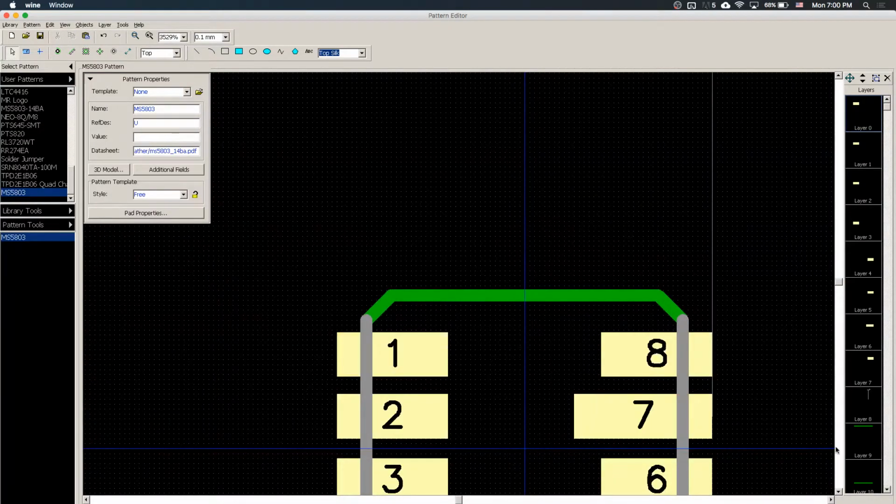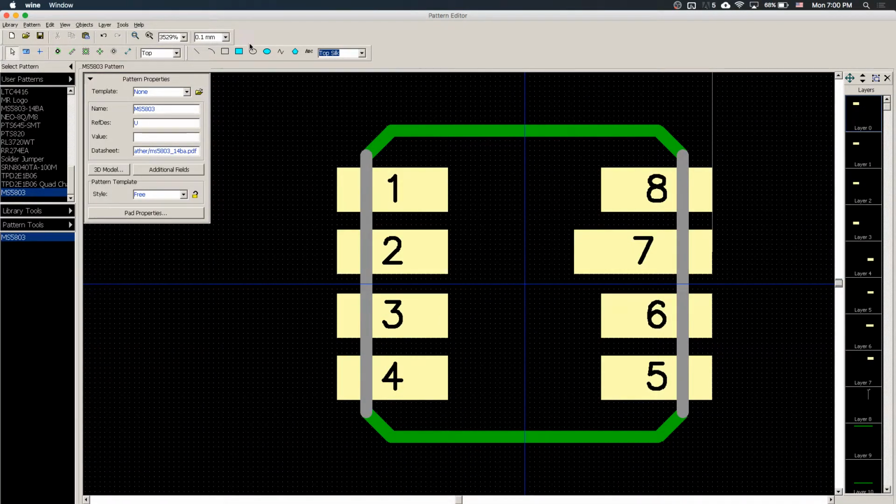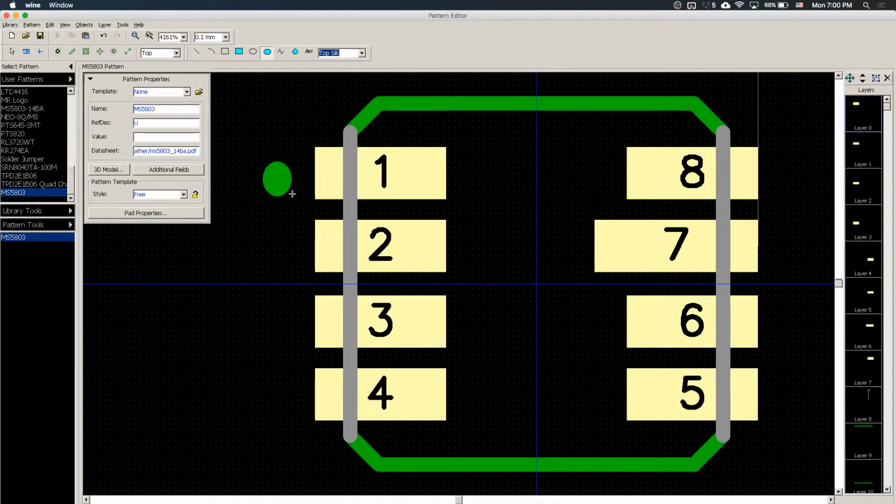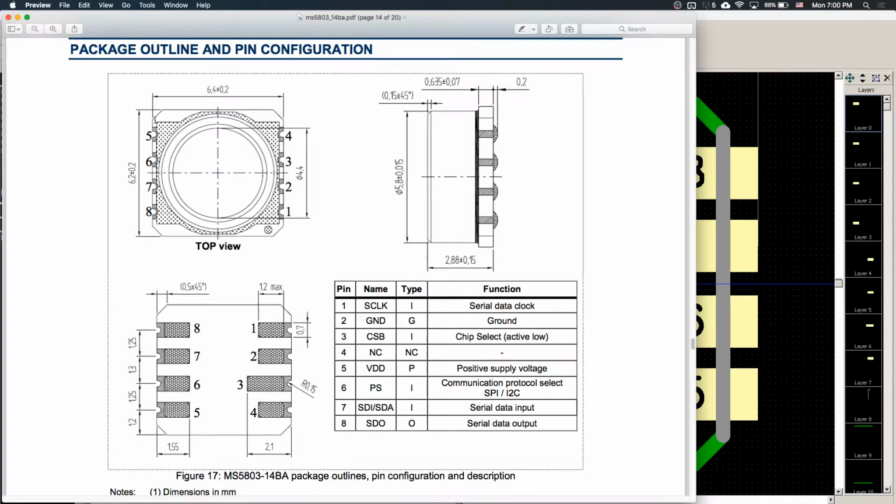The last one is a dot on pin 1, so just use the rectangular tool or the circular tool to draw a dot. But what does adding the corners add to this? Before it was just square, but why did you add the corners? Because that is what the chip is, right? It specifies that this corner is chamfered.